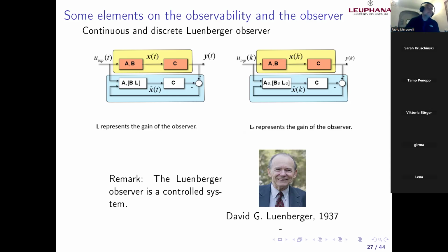Why that? Because nowadays we implement everything in the microcontroller. We use the computer for all kinds of applications, and then it makes sense to tell you about the discrete form of the Kalman filter. Basically, the continuous form is just for theoretical analysis, because in my career I have always seen the Kalman filter implemented in discrete form.